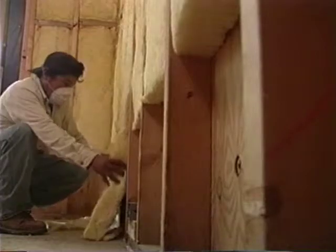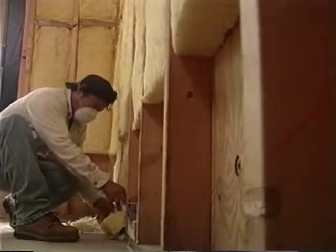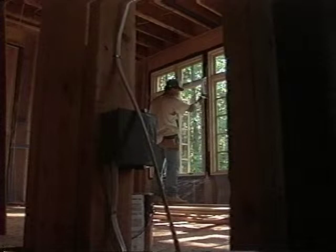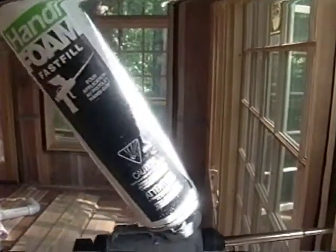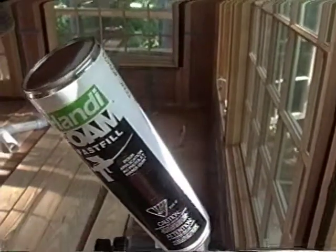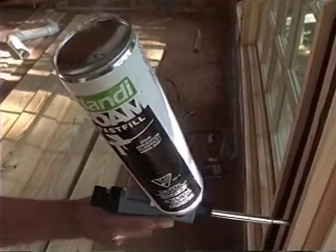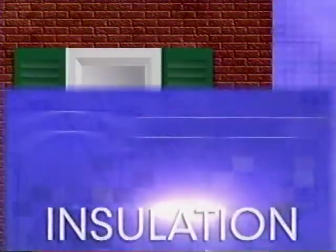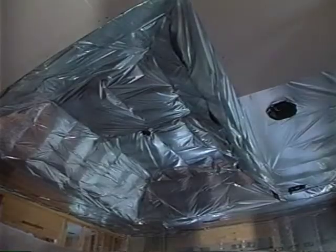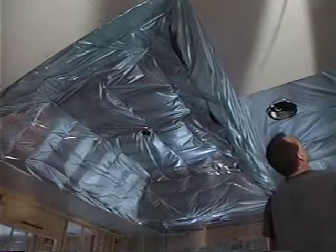Proper insulation of a home is important to its overall comfort. But without proper air sealing, some of that work just goes out the window. The air sealing of a home involves closing up any cracks or holes that allow unwanted air to leak in or out. Imagine leaving a window in your house open all day, year-round. In typical residential construction, the average home has air leaks equal to a window opening of about a foot. With proper air sealing, we can get that window nearly closed. We do that by sealing up unwanted holes in the air barrier.